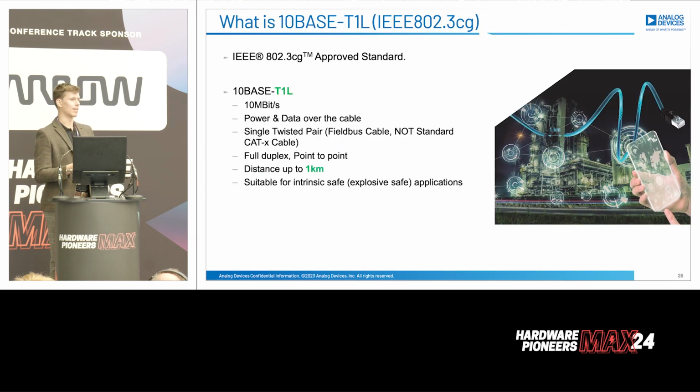10BASE-T1L, so industrial Ethernet, which I'm sure many of you have heard of. Ethernet is a fantastic solution for being able to move large amounts of data. We obviously have power over Ethernet now, which can power these edge products in industrial sectors or within large-scale enterprises such as hotels. Ethernet's fantastic because it's ubiquitous, it's relatively well understood, and the bandwidth is what people are looking for. The issue we find with the industrial customers is the reliability, the deterministic latency that is obviously required for control circuitry, and this is where something like 10BASE-T1L comes in.